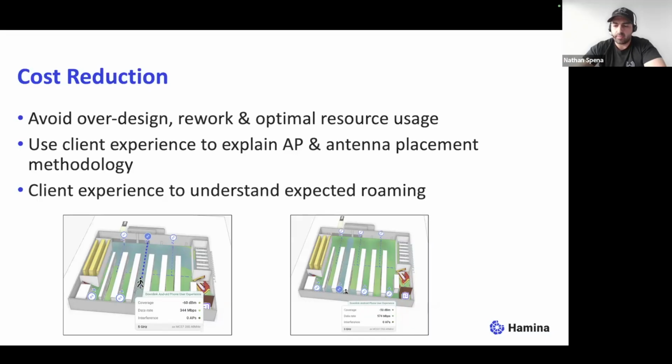Yeah, we've done that on a large scale warehouse. We had a similar issue where we tried to go on the walls. There was a rack running all the way along the walls. It was a 110,000 square meter warehouse. So we ran it in front of that rack and had patch antennas running along that back area. So yeah, we try to avoid using omnidirectional as much as possible within a warehouse environment from what we've seen in the testing that we've done. But obviously, sometimes there are times where you need it.